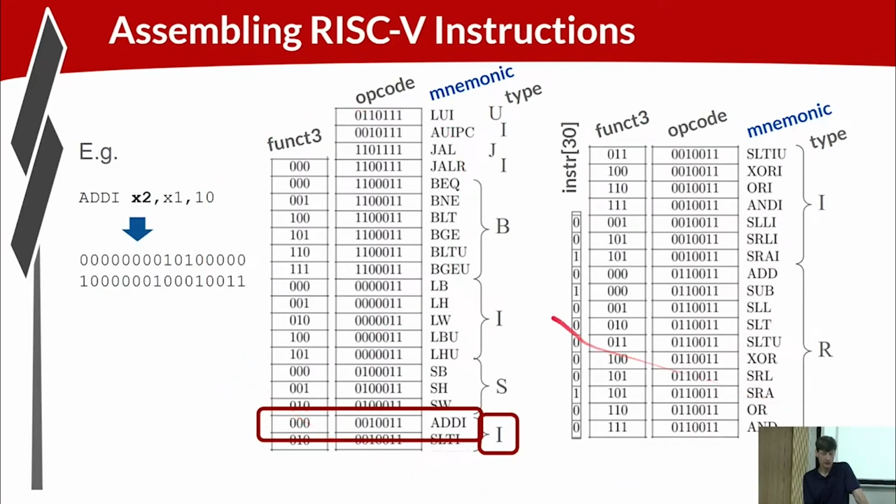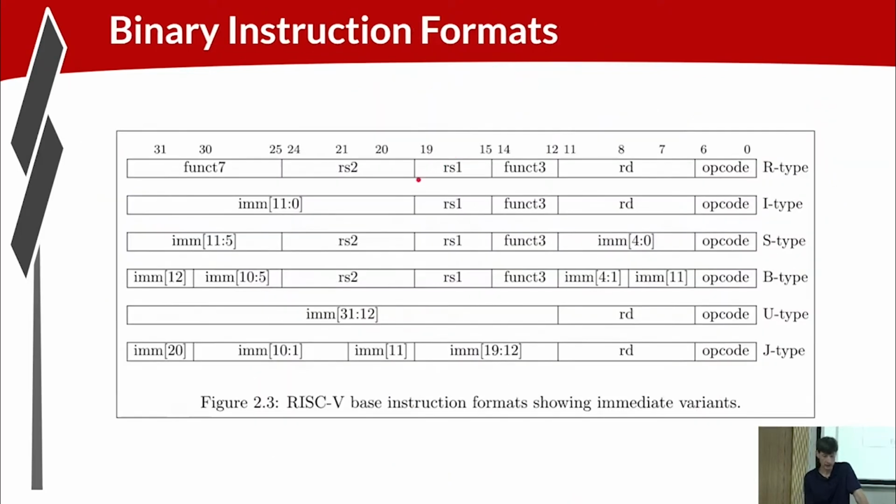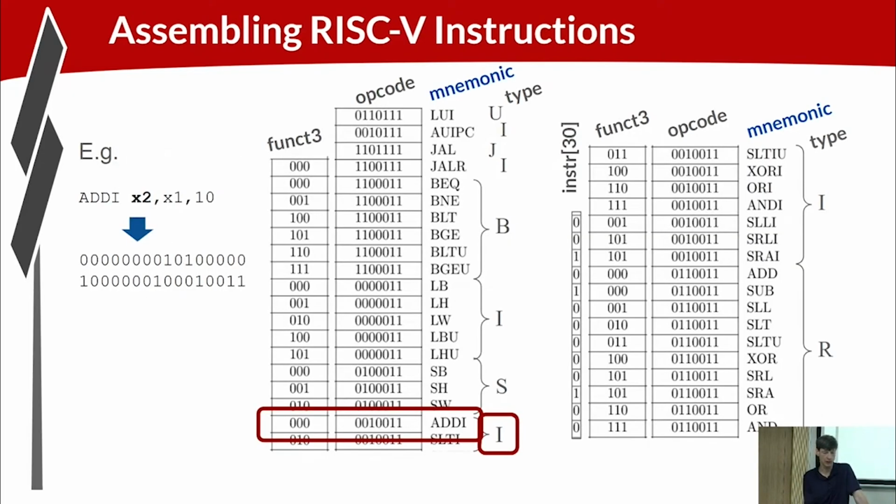This table is how we're breaking down to the specific instruction. I guess I lied before. We break down to the instruction from the opcode and func3 for the most part. I think there's only one bit of the func7 field that sometimes is used to specify the specific instruction type. So this table uses the opcode, func3, and sometimes this func7 bit, or instruction bit 30, to define which instruction we're talking about.